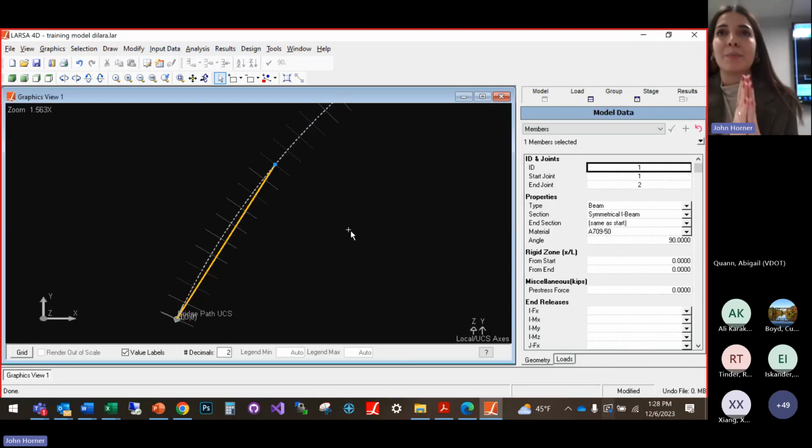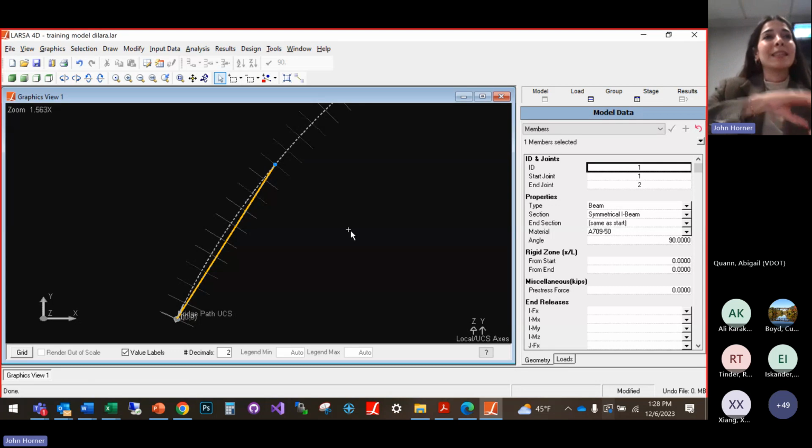We didn't mesh this beam yet. Now we will break this element into smaller segments, and we will see that some joints will be created automatically to follow the alignment. And our girder will fit on the curved geometry. So let's refine the model now.